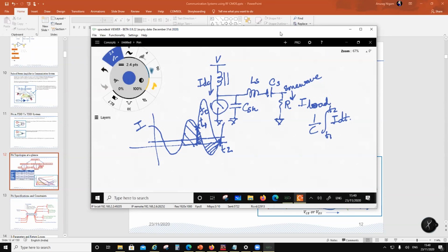So now you have a quadrature between the current and the voltage, and the net dissipation in the switch is 0. Secondly, when the switch is turned on, the capacitor was storing 0 because there was no voltage, no current. So the loss of energy stored in parasitics would be 0 because nothing was stored on the parasitic. So I have generated voltage and currents in quadrature.